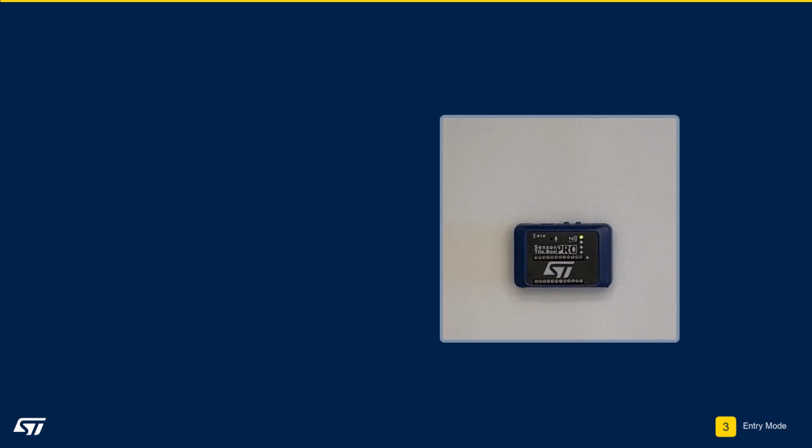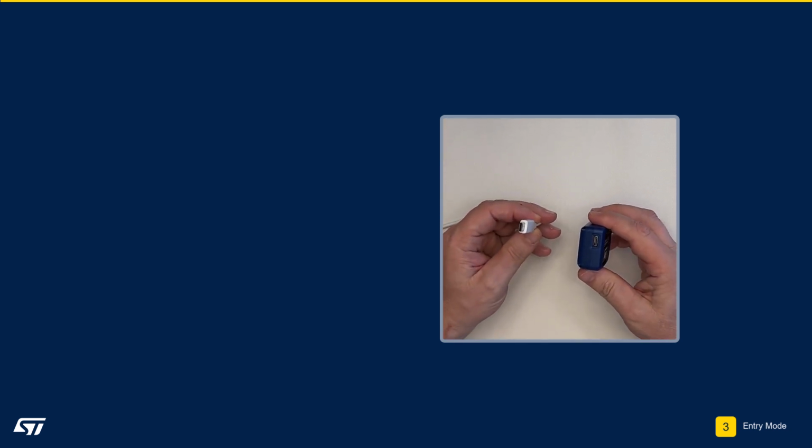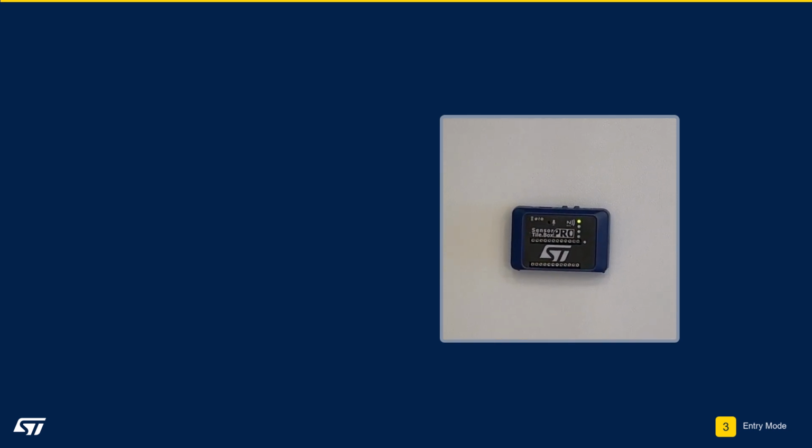If you are turning on your sensor tile for the first time, it should have come with at least a partial charge that should be enough to get you through this portion of the workshop. However, if your board does not power on, it's possible the battery does not have enough charge. In this case, please connect your board to your PC using a USB Type-C cable. Once you have powered on your board, you should see all of the LEDs cycle rapidly, then turn off, and after a couple of seconds, the green LED will turn on and stay illuminated. It's now ready for you to connect via the mobile app.